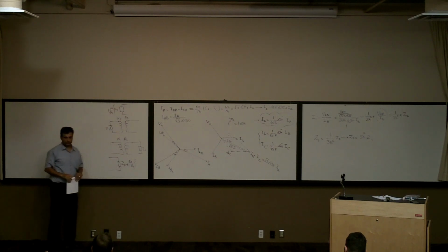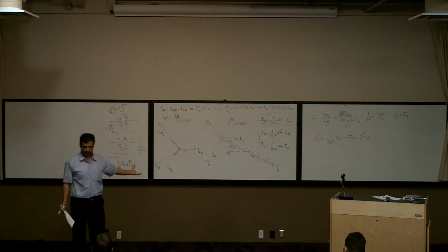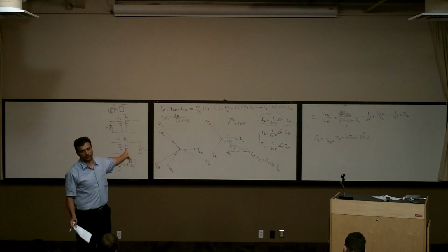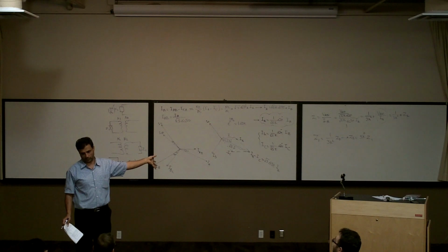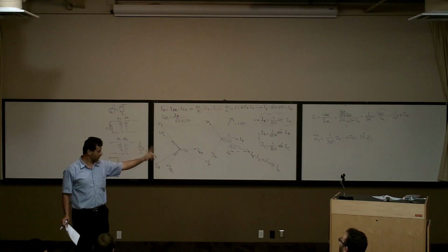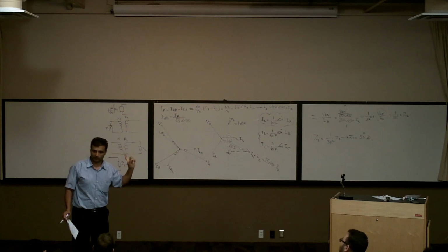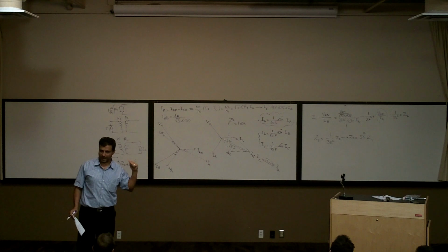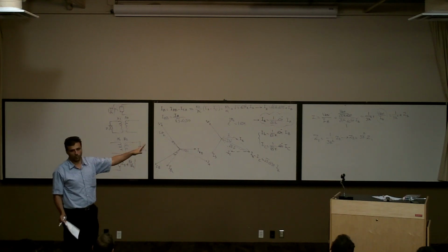Right? Just here I'm saying if you're going to transfer the impedance from a secondary, you have, for example, 2 ohm in your secondary. You want to bring it to the primary. How can you bring it? You use this equation. But be careful. K, I defined it here. It was a single phase transformation. When I'm saying N1 over N2, if I would have defined it based on the line to line, this 3 is going to go away.